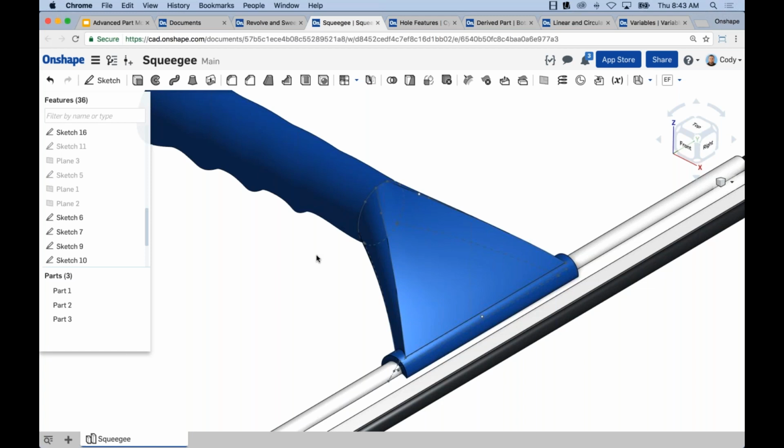I used a coincident constraint because I had the end point right there, right? But what if that line continued on? Or what if I wanted to attach the center of my circle to some point along a helix, not the end point, but just some point along a curve? I wouldn't be able to use coincident, because there's not a point there. It's just where the curve passes through my sketch plane.